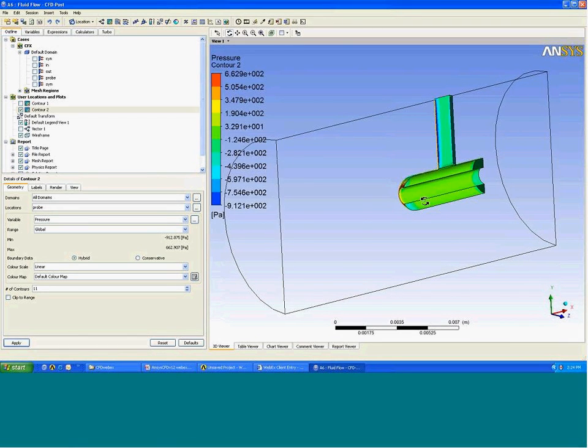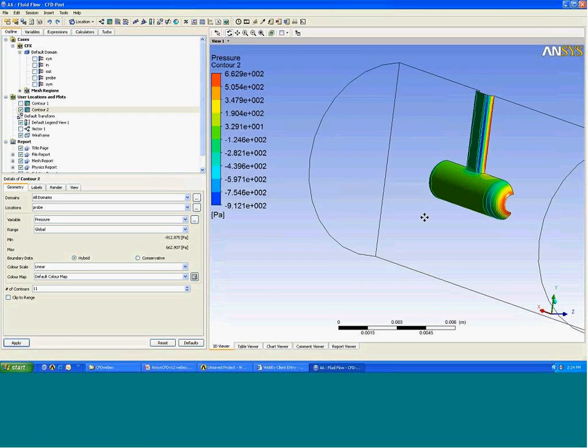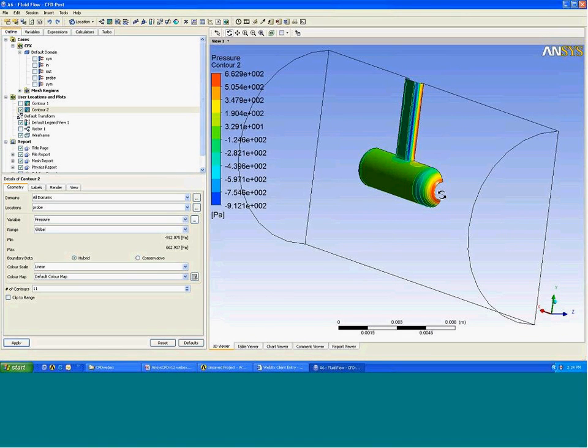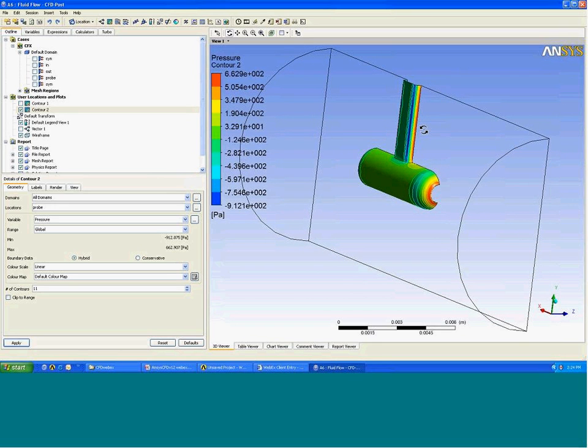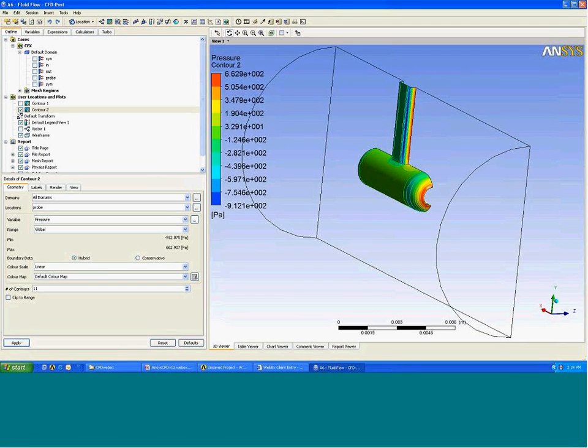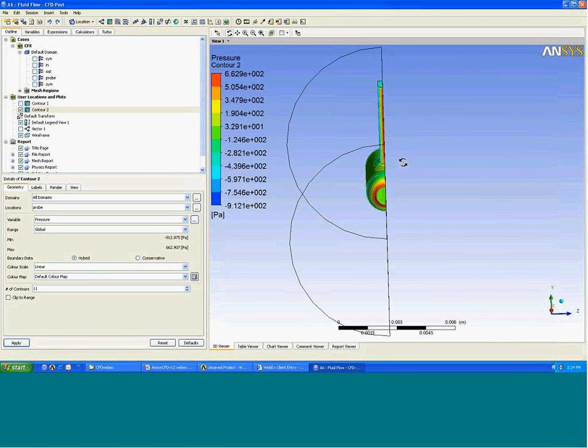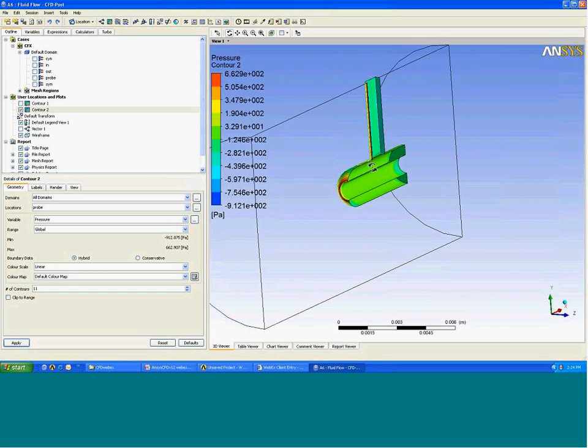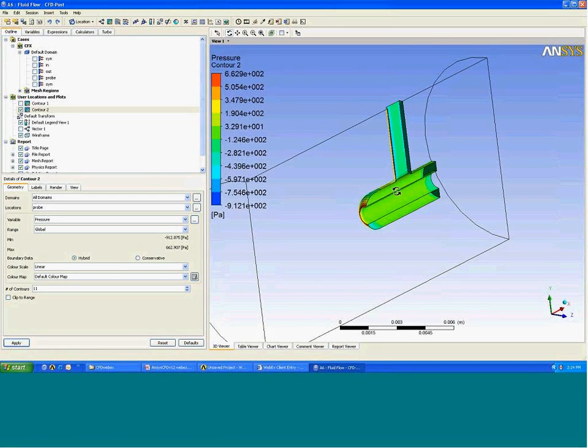And this is the surface pressure. Apparently, you see that when the flow enters the internal flow section and hits this wall, it has close to a stagnation point, so I see a higher pressure when the flow first hits the probe surfaces. And then the flow will accelerate, which creates a slight pressure drop on the contour cylindrical section, and also on the edge of the bar there. So you can generate all these plots as you wish.